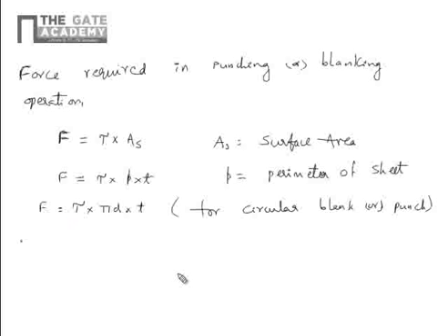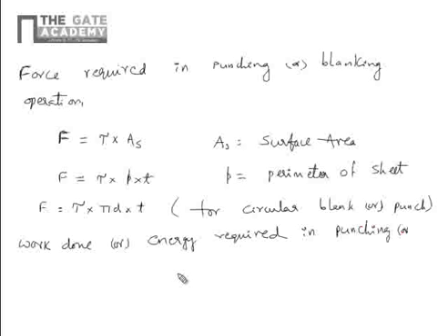Work done, or energy required in punching or blanking. Work done is force into displacement, W equals force into displacement. Displacement is how much the punch moves.